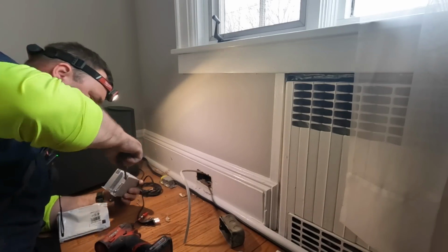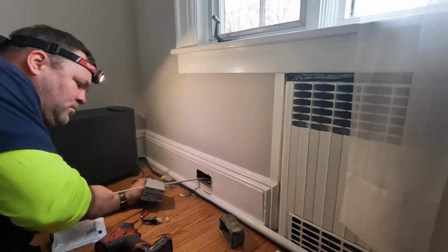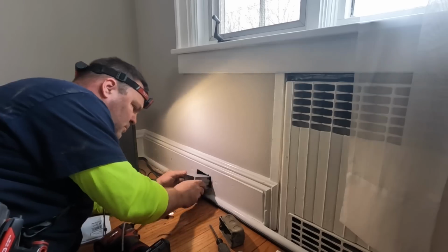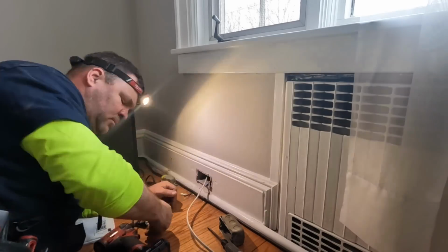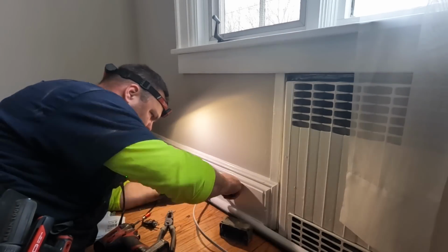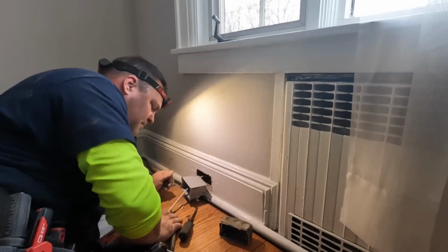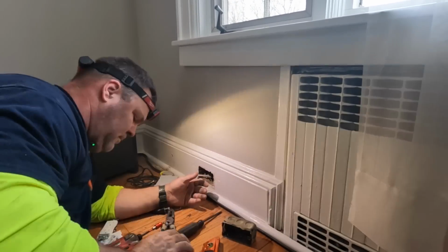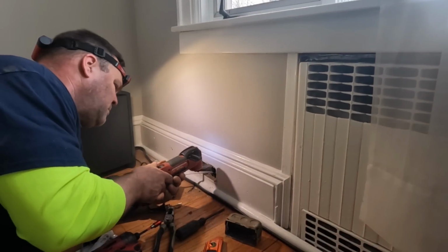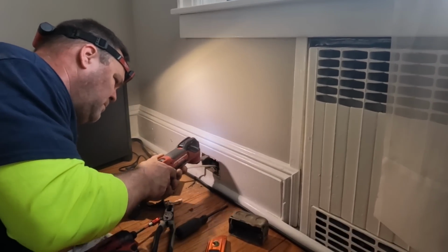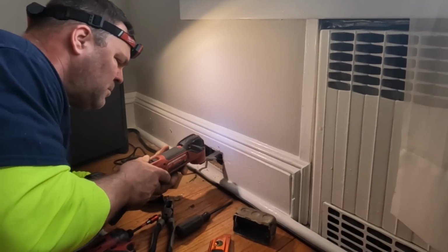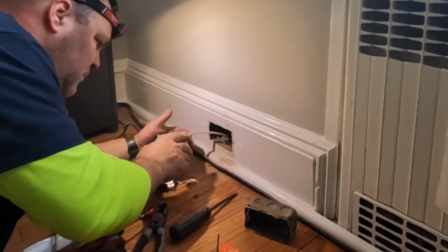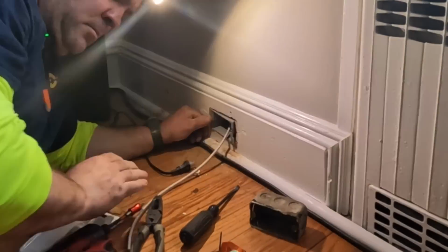So once my wiring is in place, I'm using a plastic box here. I'm trying to fit it in here, and I realize that even though I can get it in, it's crooked just a little bit to the right. So I'm going to get this started and pull it back out. Use my level to draw a straight line along the top there, and then I'll come back with the multi-tool to make the hole cut out a little bit wider, but the box and the receptacle will sit flat and level and look just right. It's worth taking the time to do this.